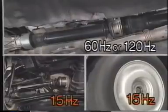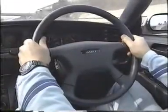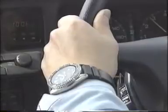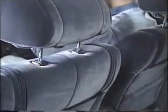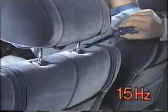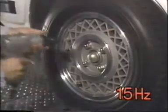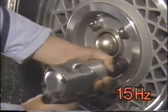If a vibration frequency analyzer is not available, there are other methods that you can use to estimate the parameters of a vibration. All you need is your hand and an intuitive knowledge about the most commonly occurring frequencies. For instance, this component is vibrating at a frequency of 15 Hertz. If you touch it with a screwdriver, you can hear and feel it quite easily. An impact wrench generates vibrations of a similar frequency.